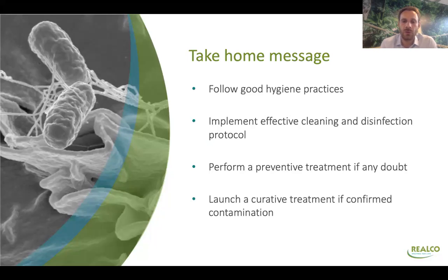And if you know that you have some contamination, remember with the biofilm topics that you have some indicators that you may have something, then you can directly go for a curative program that will help you to go back to a zero level. It means you are removing any kind of stubborn organic residue, and you are removing any kind of biofilm contamination. So your equipment is totally clean, and you can start your production without any stress.